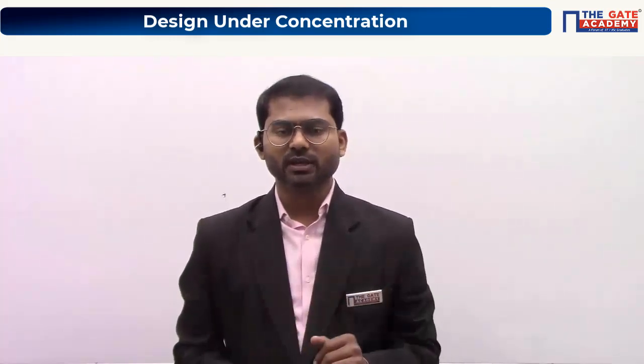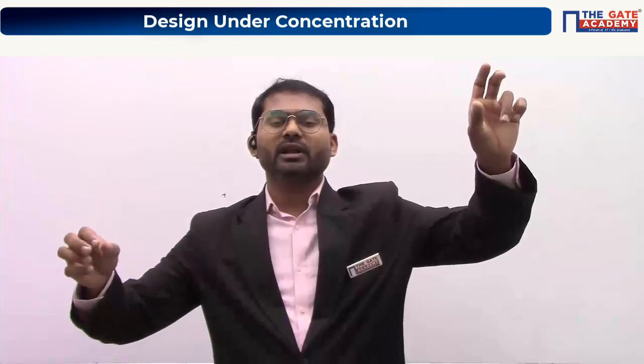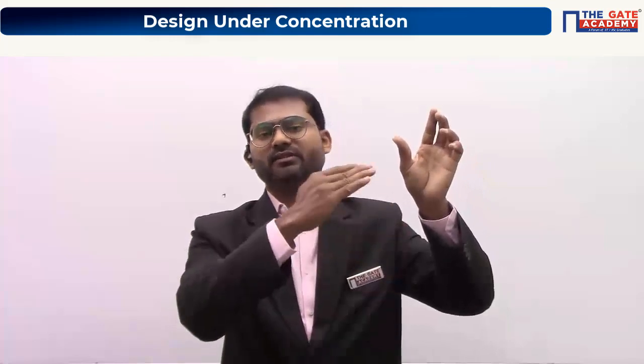Understood? Clear? In most cases, if you take the failure cases, wherever failure happens, most of the time it happens by dynamic loads. Because in static loads, generally we know the strength of the material, that is SYT or SUT. So you make sure the load will not give rise to that amount of stress. You'll know that if I give rise to a stress of 100 megapascal, it will fail, so I will not allow it to reach 100 megapascal. The stress will be some 50, 60, 70, 90 only, like that. So you know the strength of the material and you make sure it is not going beyond that. Unless due to some mistake it goes beyond that, failure will not happen.